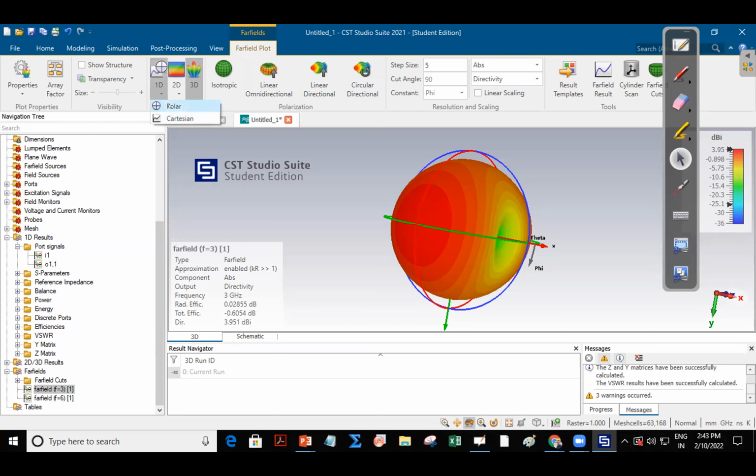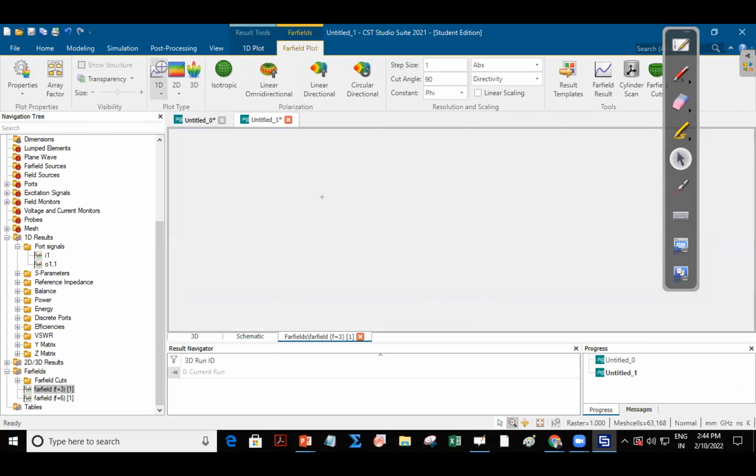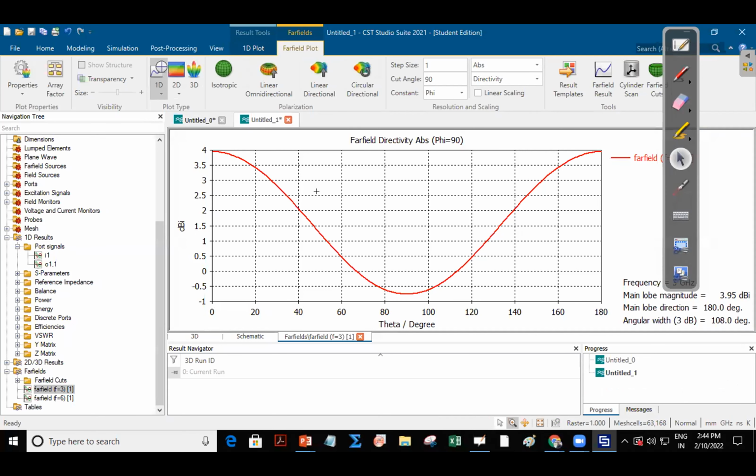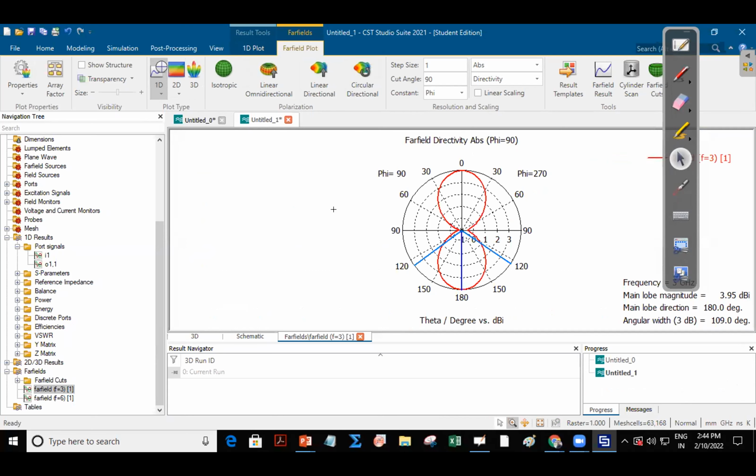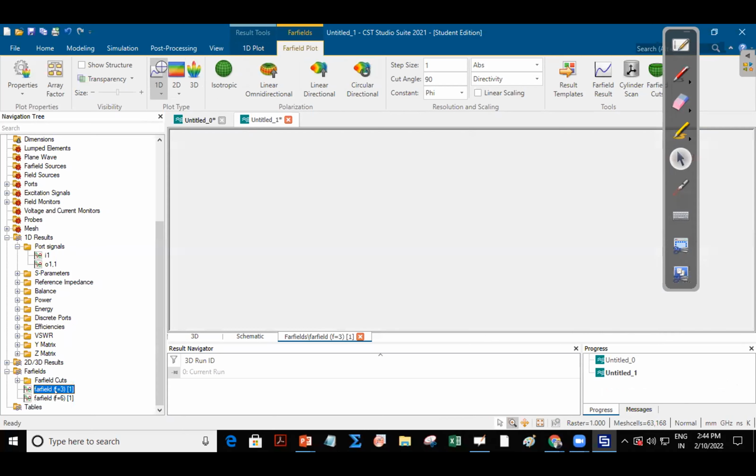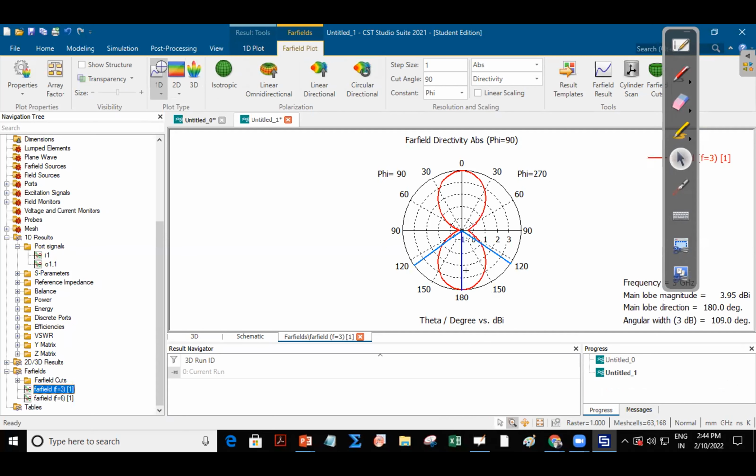Here in the 1D plot, you can also see the Cartesian gain plot, or a far field pattern that you can receive, or you can also see this in the polar plot. At 6 gigahertz, you see how abruptly it is changing. You can see the pattern which was there for higher frequency which you are observing. At 3 gigahertz, because it's nearby to the design equations only, we can say uniformly divided two fields are available. At far field pattern, it's changed.